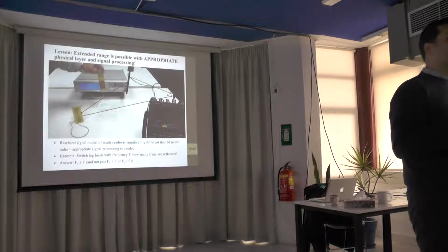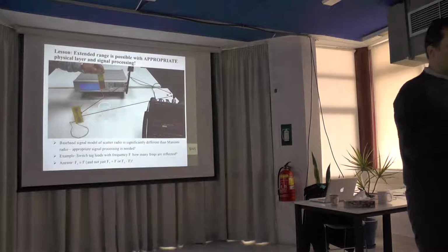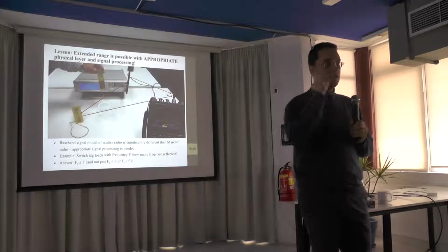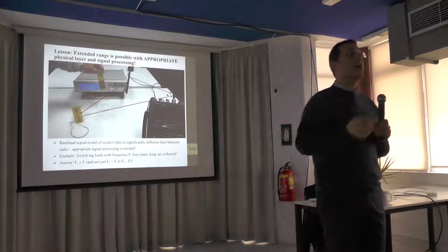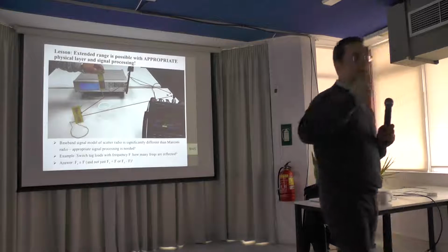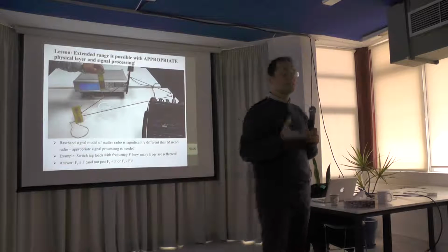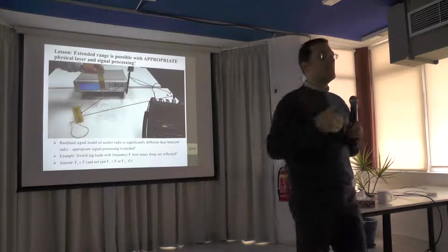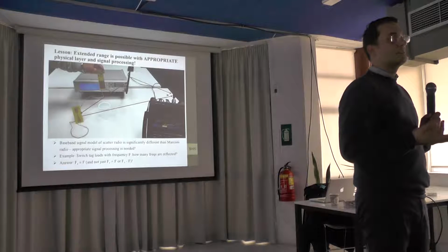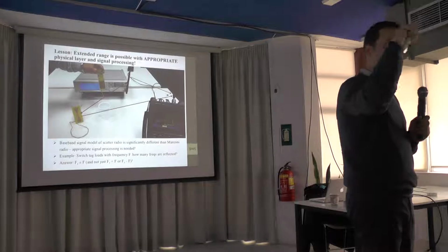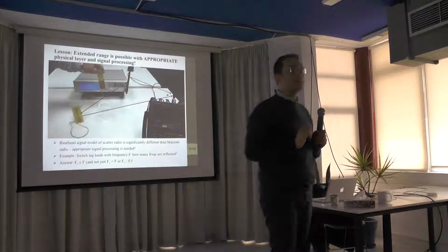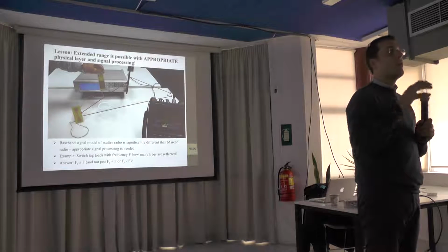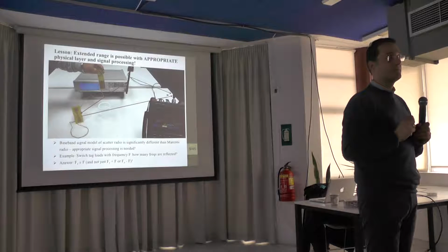If you go to the library and you carefully inspect the last page of the book, you will see a sticker that has a little antenna and a very small chip. And whenever you go and check out the book, they basically place it on a flat panel with an antenna that reads this tag very similarly to this principle. And basically, you can check out the book, right? It's a small coil antenna with a very small chip inside, which is batteryless. It takes energy from the illuminating field. And the field comes from that panel antenna on the desk of the librarian. Okay?